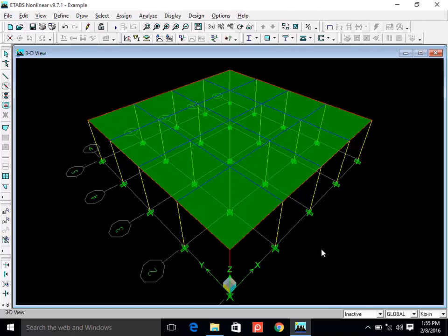One, you have supports, and in between you can choose several nodes, right? On every node, at the end of analysis, you will get shear force, bending moment, and displacements, right? So, when you convert a solid surface into a mesh, you are actually creating nodes, okay? And in the end, you will get the forces and displacement at every node, okay? But this is not the only objective.